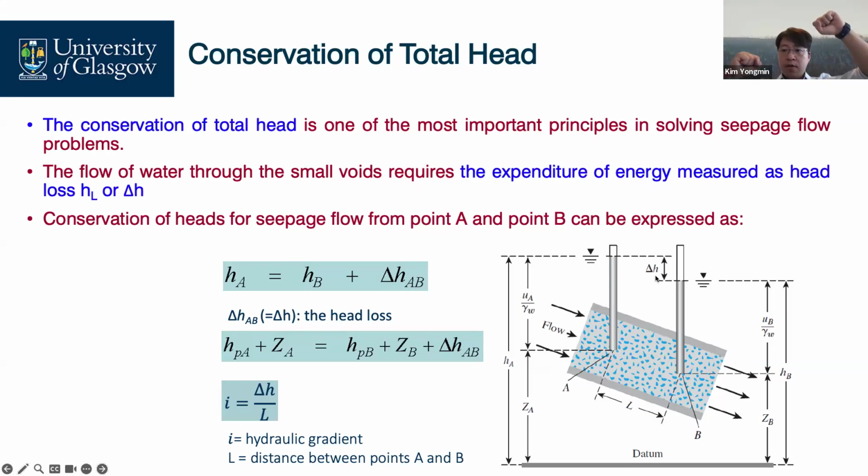Then we know the length of water flow, and the ratio of the total head loss over the water flow length is the hydraulic gradient. No unit, non-dimensional.